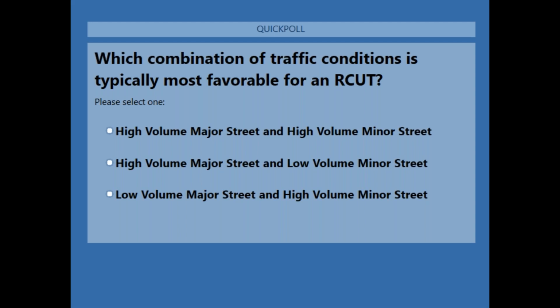With the Michigan U-turn or median U-turn, it's left turns from both the major and minor street that are typically pushed down to the U-turn bay to come back. So the median U-turn or Michigan U-turn is a similar form of intersection, but a little different in terms of what directions get relocated. They are cousins. They're very much related, but just slightly different in terms of which movements get redirected to the U-turn bay. Great question.